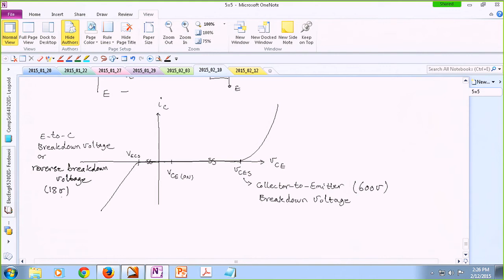In most typical IGBTs, you are not allowed to apply a negative voltage across the device unless that negative voltage is only like 1 or 2 volts or something like that. You cannot apply negative 600 volts to a 600 volt IGBT, okay? The device is not going to handle it. Although there are IGBTs that are recently being introduced to the market, a little bit more expensive, that can also handle negative voltages if need be. This is as long as the device is off.